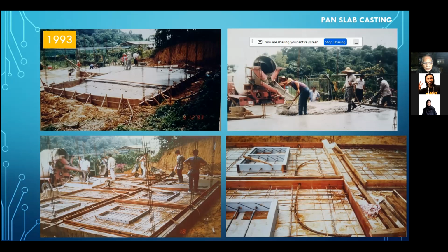I put the wall, I put the window frame, and you can see the welded fabric used for the wall. It's also around the window frame. I use a very small one, about 8 mm diameter, to cast the wall, and then I lifted the wall. So instead of doing the column first, I only put the column reinforcement, as you can see, standing up there.